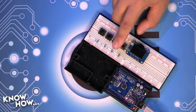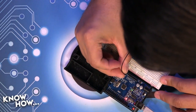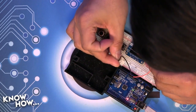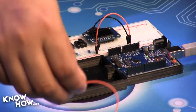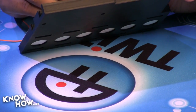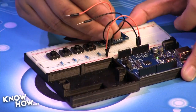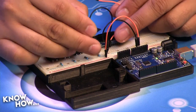All right, so let's go ahead and start wiring this up. I'm going to need power from my board, and I'm going to steal power from my Arduino, as we've got those 5-volt pins. I'm going to put them right over here. I need it for my buttons, and I'm also going to need it for my I2C screen. So let's get another set of leads. This gets a little tricky. Just remember this first pin here, that's ground. The second pin here is going to be my voltage. Can't quite see it on the shot. There we go. So that pin is ground, that pin is my voltage, and I just...